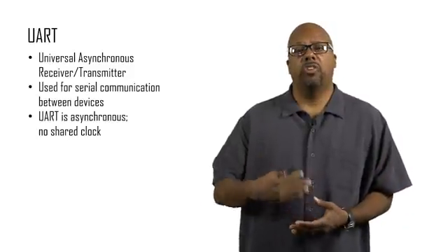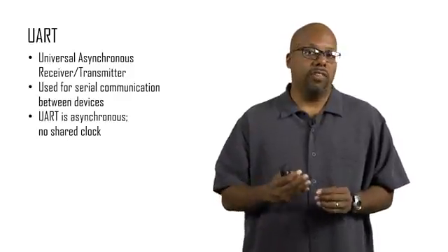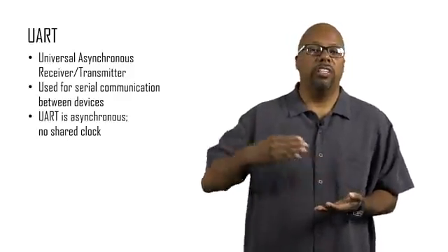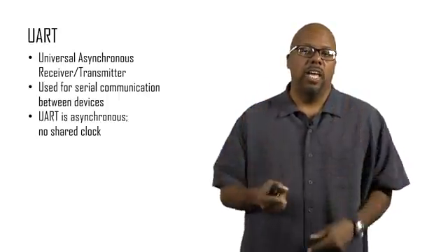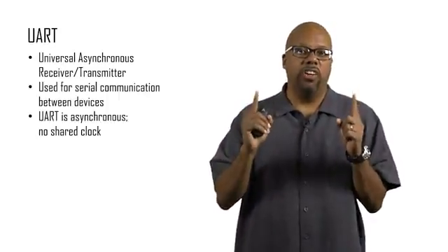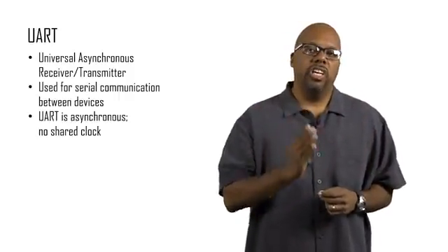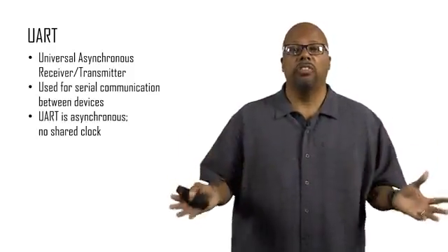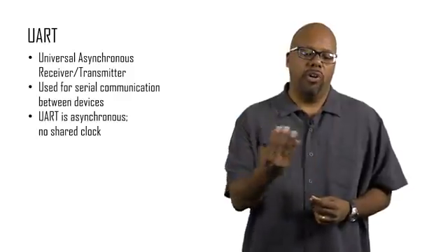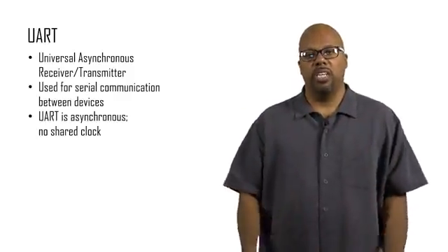The system clock is going to run at a certain frequency. And the rising edge has to travel from wherever the clock is generated to the chip. There's a certain amount of distance. Maybe it's traveling this far, but these things are fast, so this far is a long distance. So it is important that the rising edge arrives at every destination at the same time, or very close to it. That's the assumption for all of our systems, that all the parts on your device that are receiving the clock receive the rising edge at the same time.